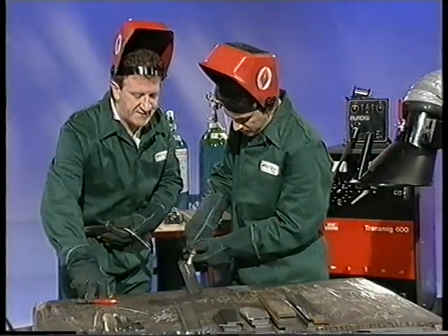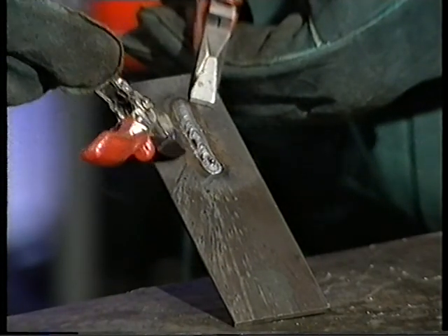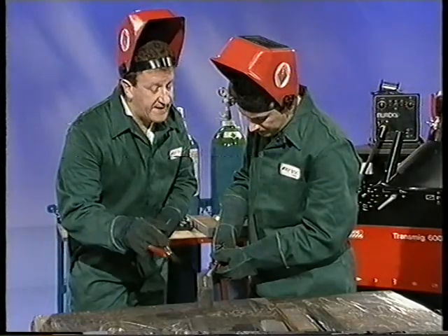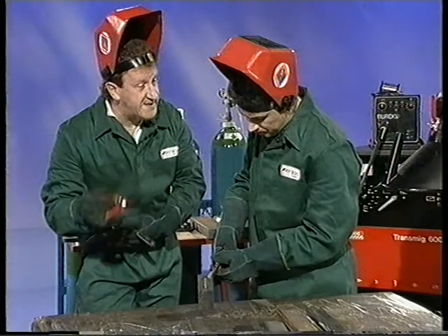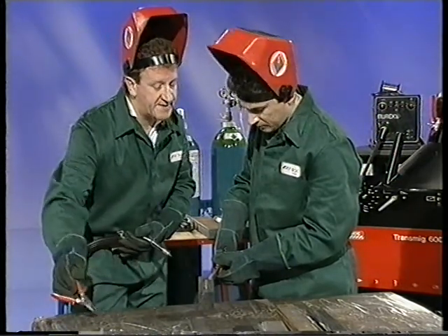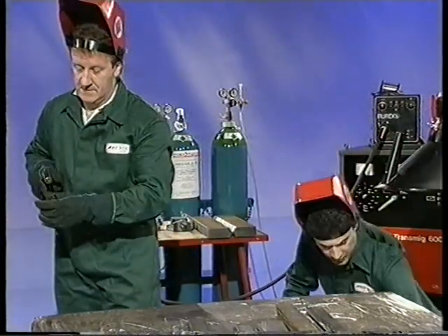A lot more spatter produced, and if you look at the edges of the weld there, how that looks quite cold compared to the previous weld bead on the other inductance tapping. It isn't to say that the inductance tapping doesn't have uses, it does in other applications, but in this application on carbon manganese steel, the higher inductance tapping is the better one to use. Right, okay. So, if we put that back again.